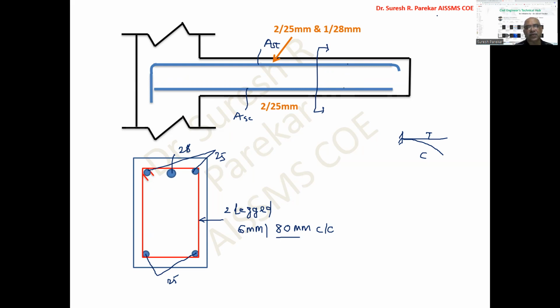In the exam also, you can try this. You have to consider 50% steel curtailed, and for the remaining 50% find the moment of resistance, and equate that with the bending moment, which is WL square by 2. If I go for this, then the video will be lengthy again. You can do this easily.